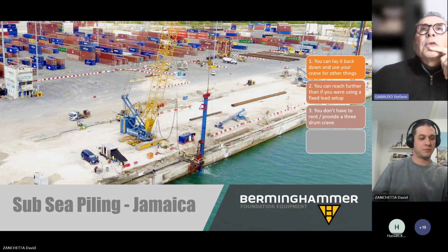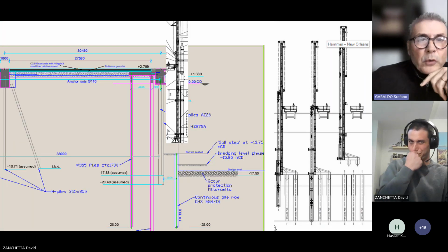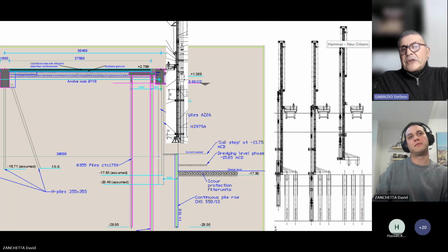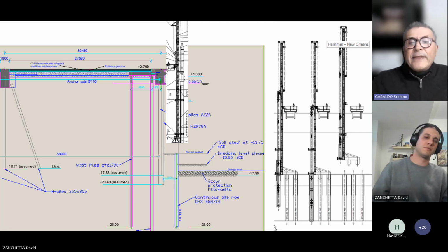So if we go on to the next slide, you see that the construction is actually shown, the existing construction is shown in pink and gray. So that was our existing port. The port is perfectly fine the way it is. They just needed to dredge. So what we needed to introduce, in this case, was a pipe-to-pipe wall of 558 millimeters, so 22 inches roughly, 14 meters, 15 meters in length maximum.